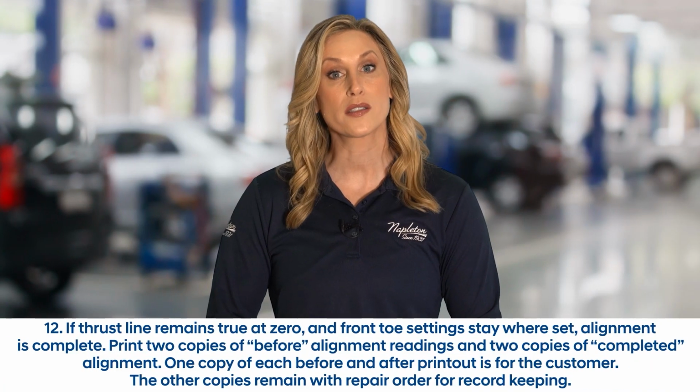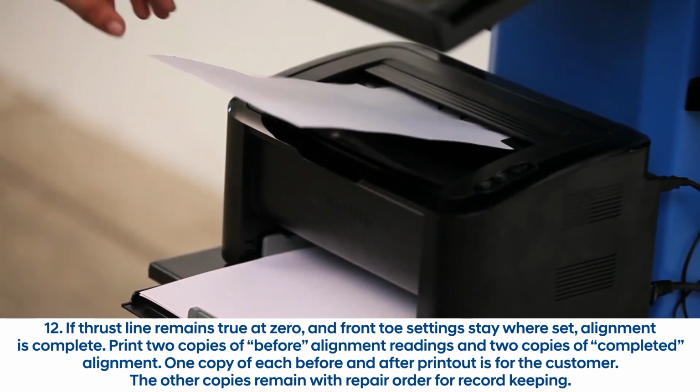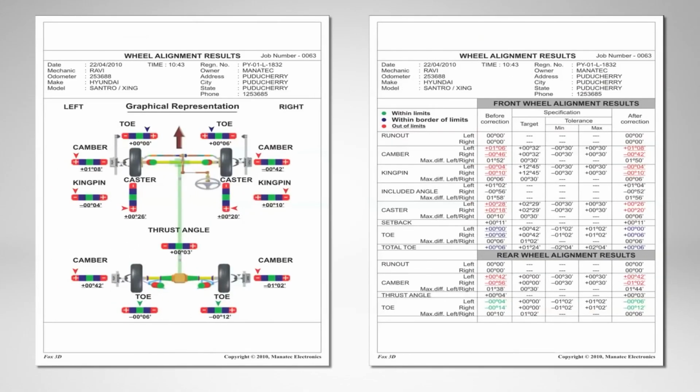12. If thrust line remains true at 0 and front toe settings stay where set, alignment is complete. Then print 2 copies of before alignment readings and 2 copies of completed alignment. 1 copy of each before and after printout is for the customer. The other copies remain with repair order for record keeping.